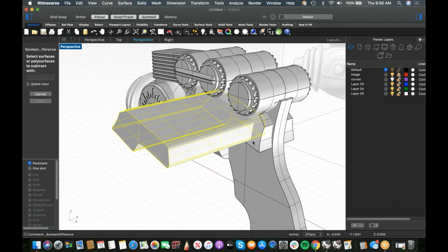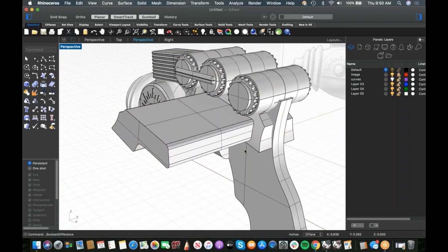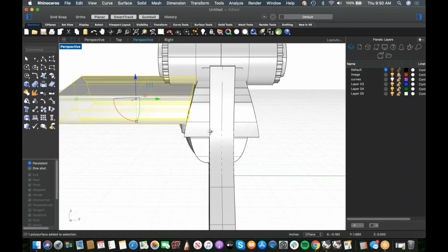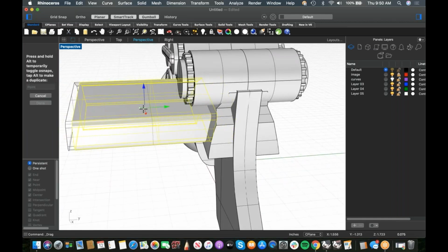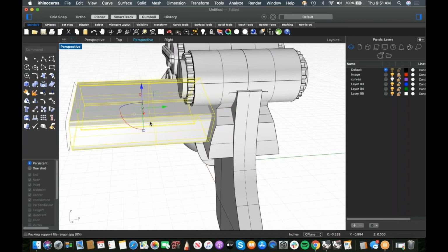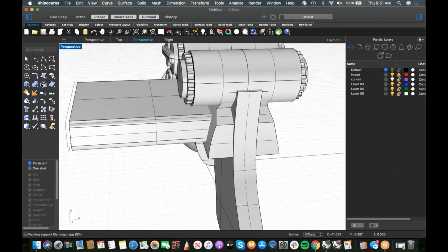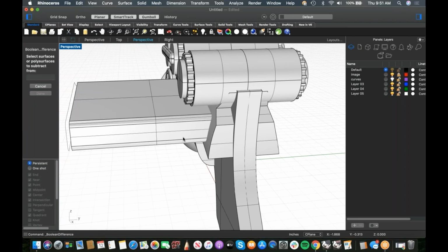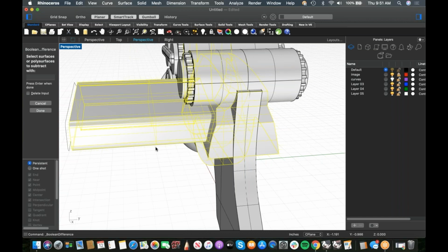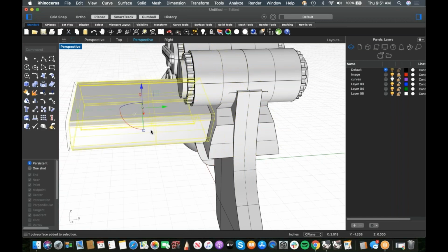What that's going to do is cut a contour on the back of this that I can then take and shove into the model to make my inset, and it'll be inset following the surface instead of inset with a flat bottom on it, which gives me a nice result. I show people this all the time and they're always like, oh my God, I never thought about that. It's like, well, you should take one of my classes. So there's our logo inset.